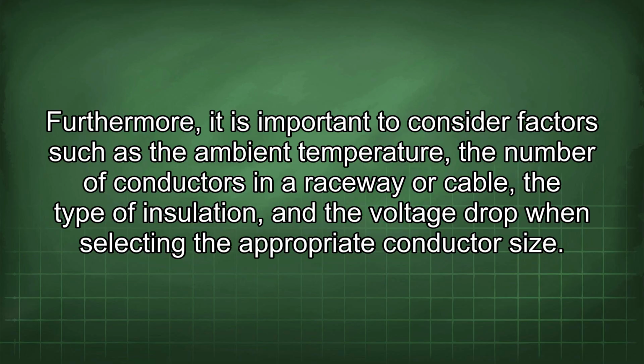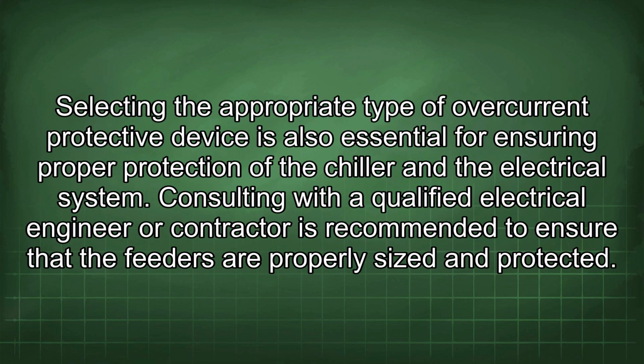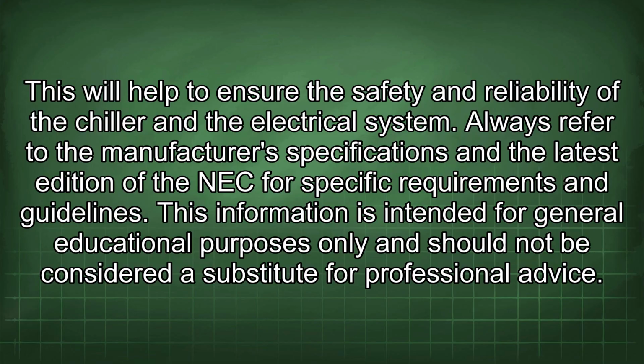Furthermore, it is important to consider factors such as the ambient temperature, the number of conductors in a raceway or cable, the type of insulation, and the voltage drop when selecting the appropriate conductor size. Selecting the appropriate type of overcurrent protective device is also essential for ensuring proper protection of the chiller and the electrical system. Consulting with a qualified electrical engineer or contractor is recommended to ensure that the feeders are properly sized and protected. This will help to ensure the safety and reliability of the chiller and the electrical system.